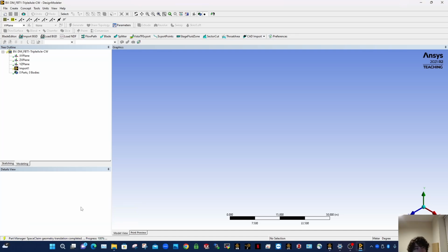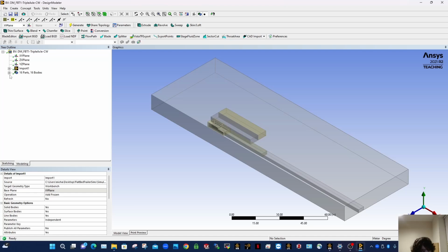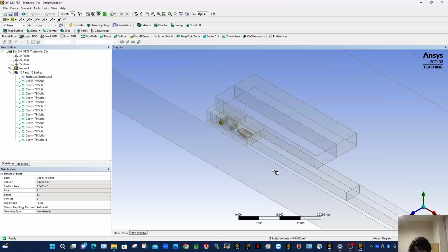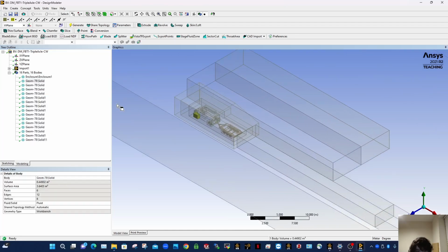So 100% cool. Right, so highlight all these faces, holding control to highlight multiple faces. Change them all to fluid. Now this is the naming convention I have for these. So that one there I call BOI1. That there I call BOI2. That one is BOI3. That's BOI mirror.